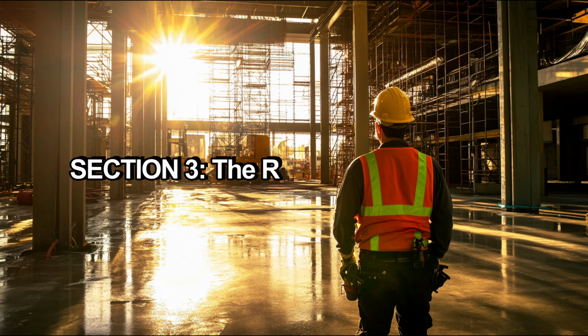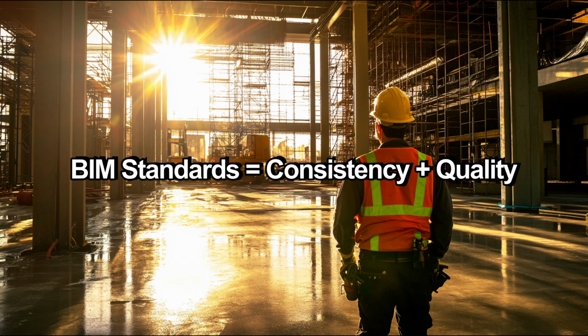This brings us to the role of standards in BIM, a critical component of successful project delivery. While industry-wide standards like ISO 19650 or the AIA BIM standards provide a framework for best practices, it's crucial to understand that each office will likely have developed its own internal BIM standards. These internal standards are tailored to specific workflows, tools, and expectations of that office. They dictate everything from how models should be structured to how data should be managed, and even how different teams should collaborate within the BIM environment. One of the key ways these standards are enforced is through the use of templates, content libraries, and detail libraries.